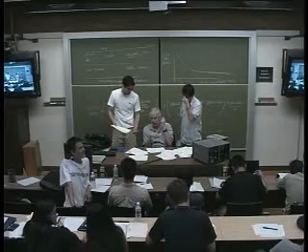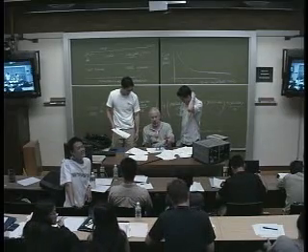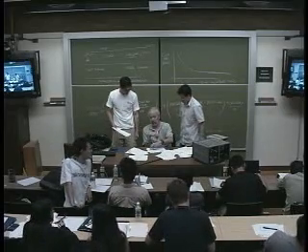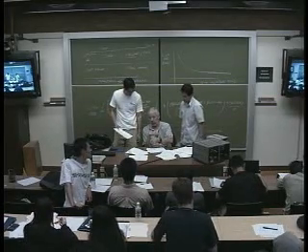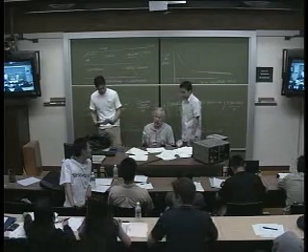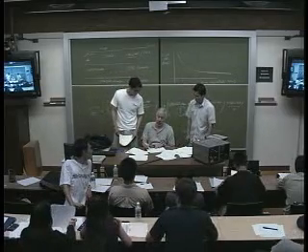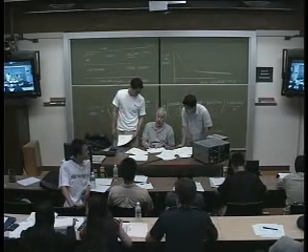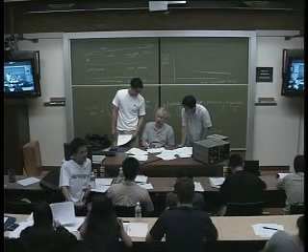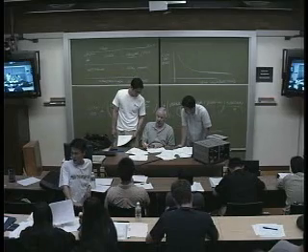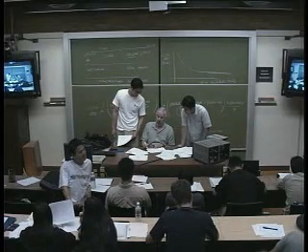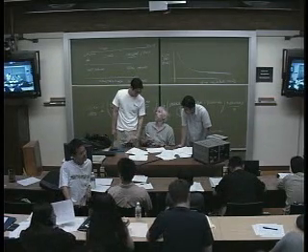So that's our big GM. Big GM is the GM of this thing plus this current divider here, between 1 over GM looking this way and R0 looking this way. Remember how you do it. You short this, right? And that shorts this node here. So looking up into here, it's truly 1 over GM, and looking down here is R0. So it's just R0 over R0 plus 1 over GM that is the reduction. That's the reduction factor right there?